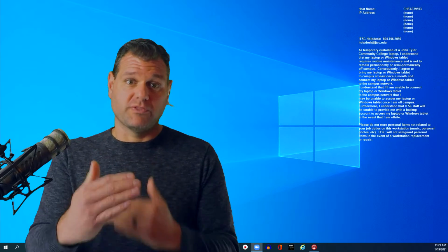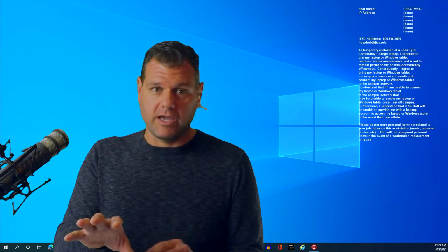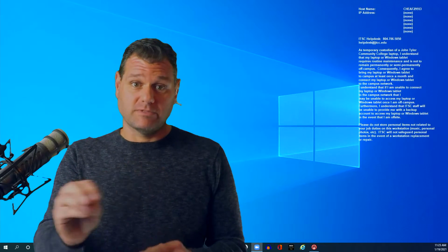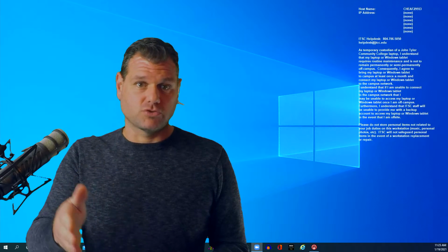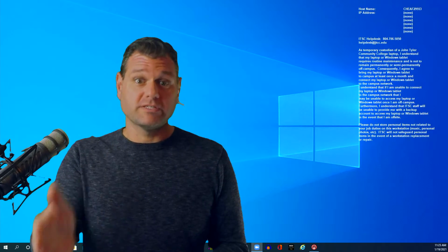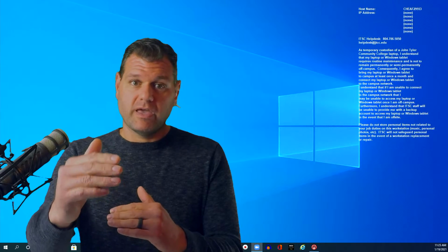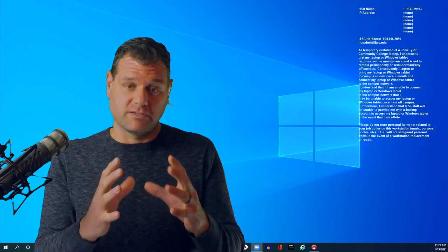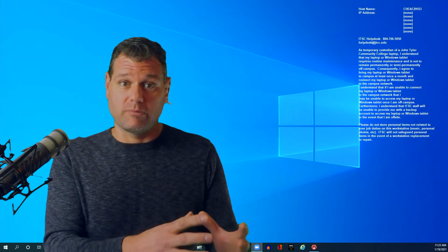You put those things within this zone and you say, okay, if this fault happens, I want you to go ahead and activate or deactivate this MCR master control relay or reset instruction, and you're going to take all those out. Now, I keep saying master control relay because that is the actual real device, and we'll talk about that later.